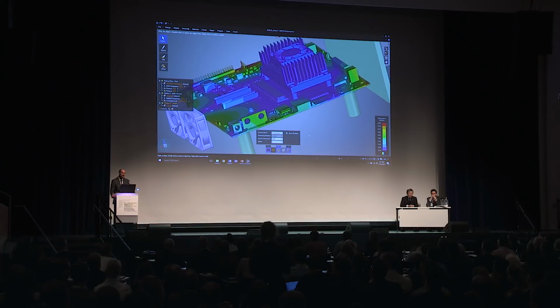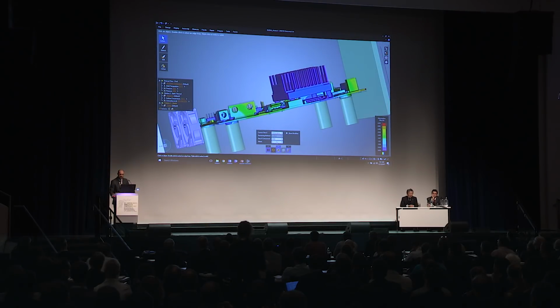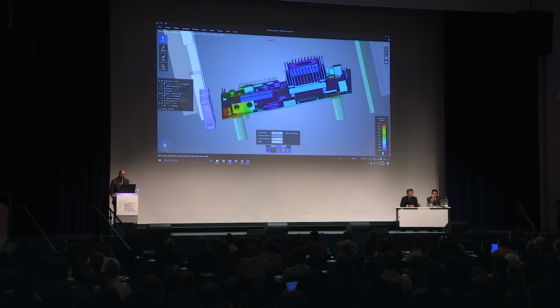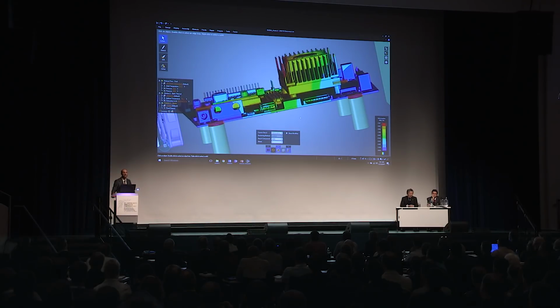And still, maybe as a designer, I don't just want to view how these are rotating, but actually before that, you might notice. Let's take a look at this first mode. You'll notice here this is free vibration. So let's add more control. Let's pick maybe the support face down here, find all the faces that are the same size. And again, watch this. While this simulation is running, while we're looking at the animation, we can add a boundary condition. Again, pay careful attention. You'll notice suddenly that mode shape is going to change.